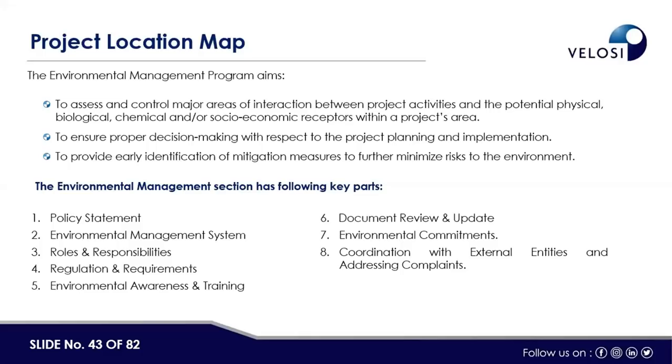There are different kinds of projects. Depending upon the project, for example, if the project has a high or more negative impact, then the authority requests for the environmental impact assessment. And if the project has a less or minimum negative impact, then the regulatory authority asks for the IEE, initial environmental examination. So initial environmental examination and EIA are the same thing. The only difference is the nature of the project. But the management plan is a separate plan that is required during the life cycle of the project.